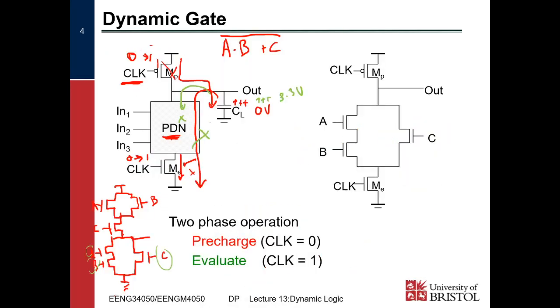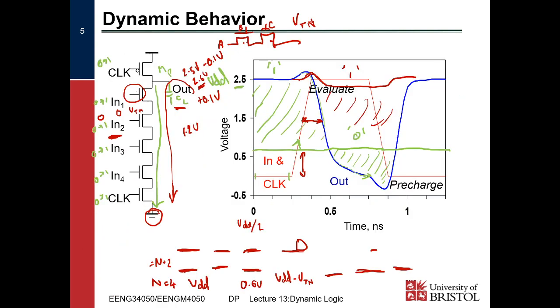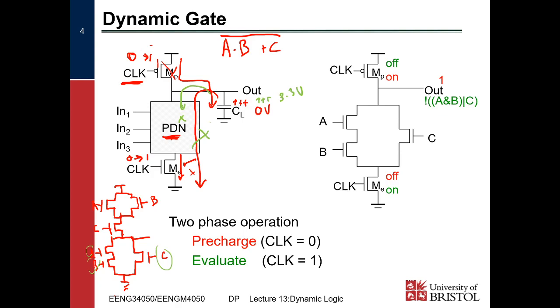So we have this issue when the pre-charging phase has passed, the output voltage might drop down below the threshold voltage, which will introduce a 0, but what we're looking for is 1. So what if we implement the pull-up network? So instead of just putting a pull-down there, is that going to work? So you're saying what happens if we have an evaluate transistor up here, then we have a pull-up network. Yes, and a clock connected to a PMOS pre-discharge transistor like that. Yeah.